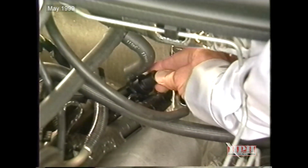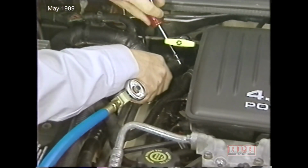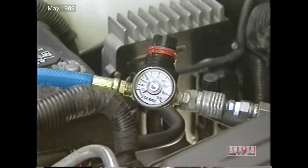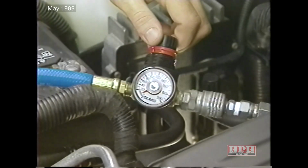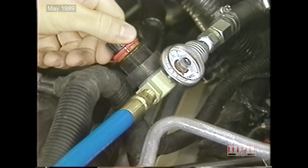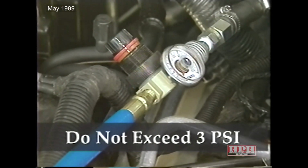An air test, which involves manually pressurizing the engine crankcase. To do this, disconnect all crankcase breathers and plug them. Then attach an air hose with a pressure gauge and regulator to the oil dipstick tube. Gradually apply air pressure from 1 to 2.5 psi while applying soapy water at the suspected leak source. If bubbles appear, you know you've pinpointed the leak. When applying the air pressure, be careful not to exceed 3 psi, or you could damage seals or gaskets.